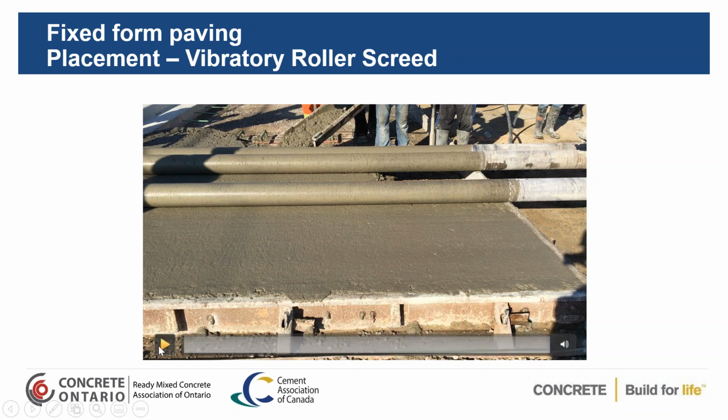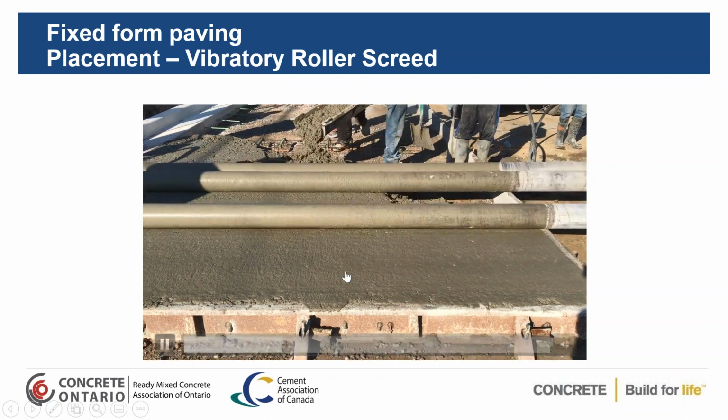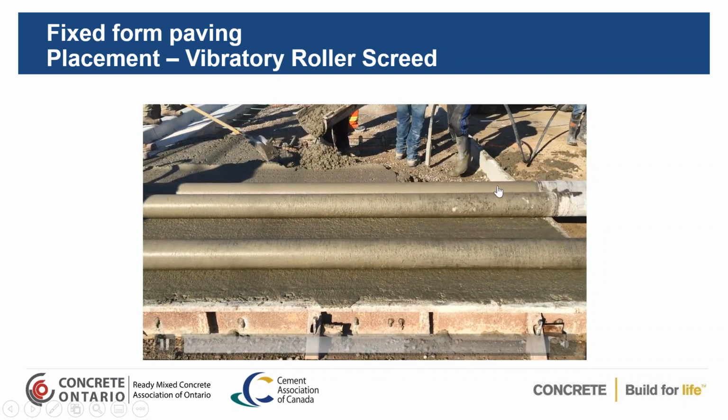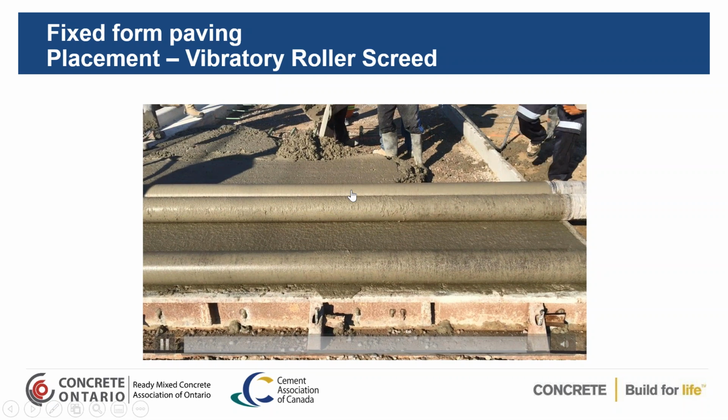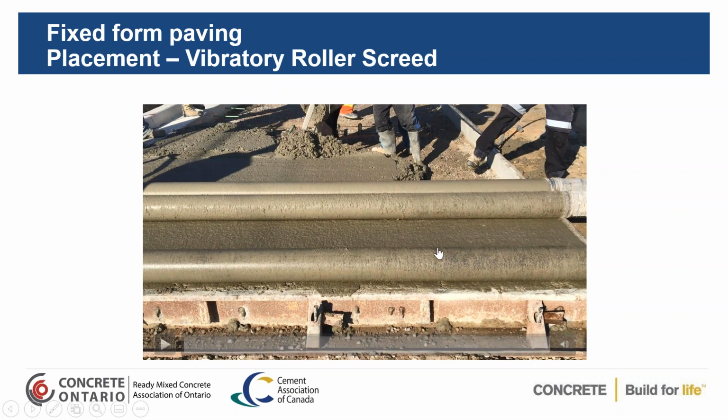And here's just another showing the operation of the roller screed. See, these two are stationary. The one back here is spinning and vibrating, so it's helping consolidate the concrete. These ones are leveling the concrete out.